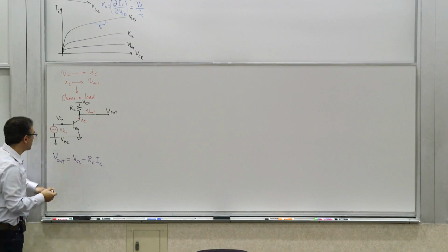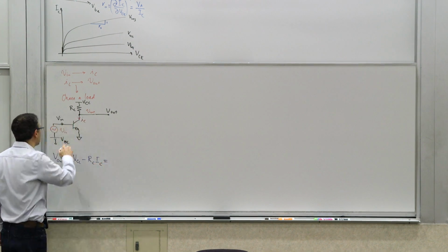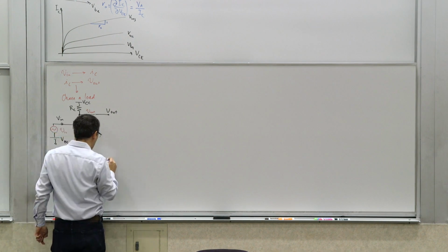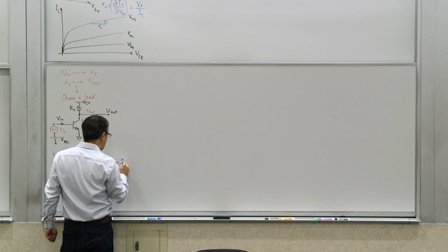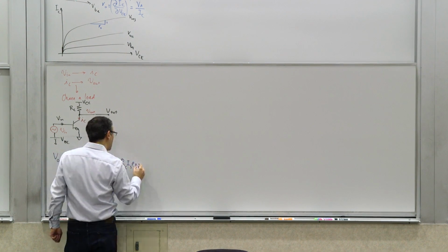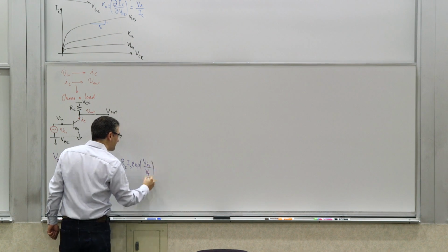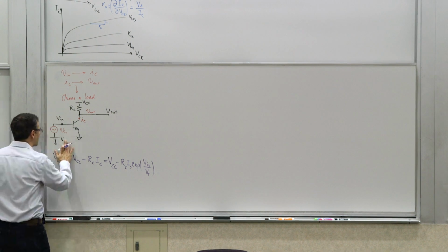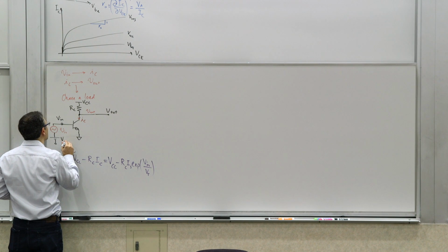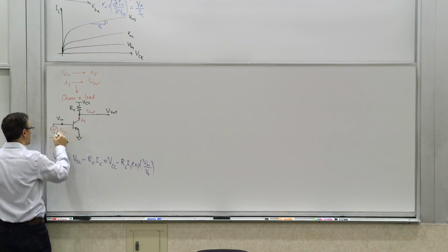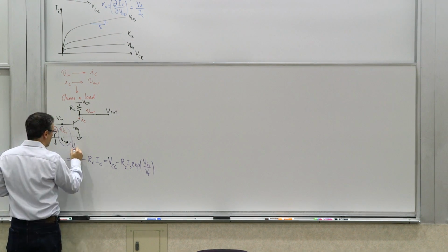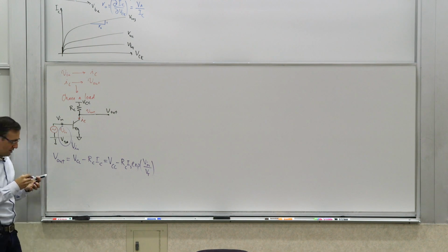But what happens is, we have an expression for IC in terms of our aggregate Vin, because that's the behavior of the transistor. If you're in the forward active region, then this is VCC minus RC IS e to the Vin over Vt. Because now VBE is the entirety of Vin. I think in this case it would make sense to call it Vin. This whole thing is capital V lowercase n, which means the whole thing in our notation. Okay, so that's what that is.